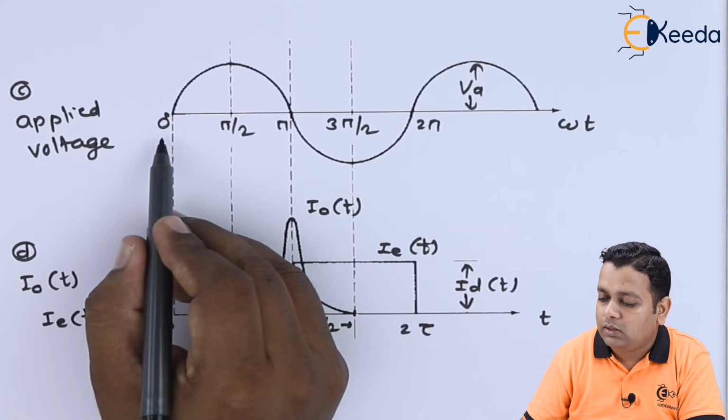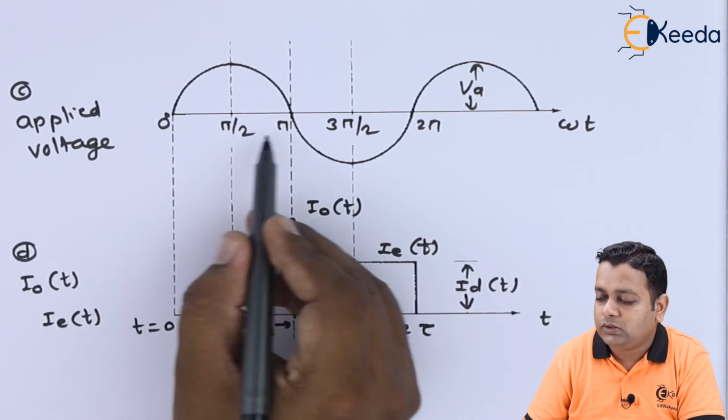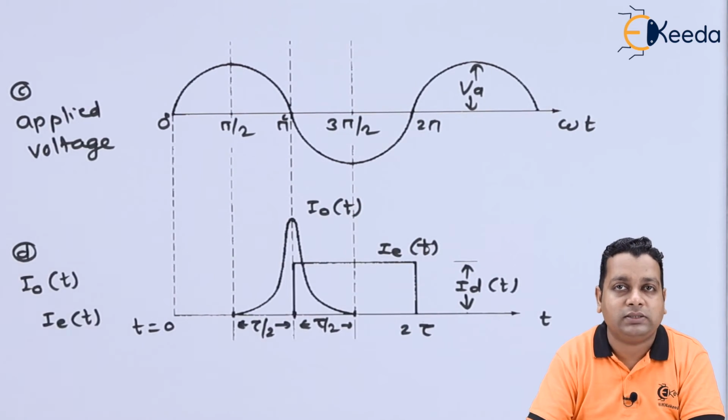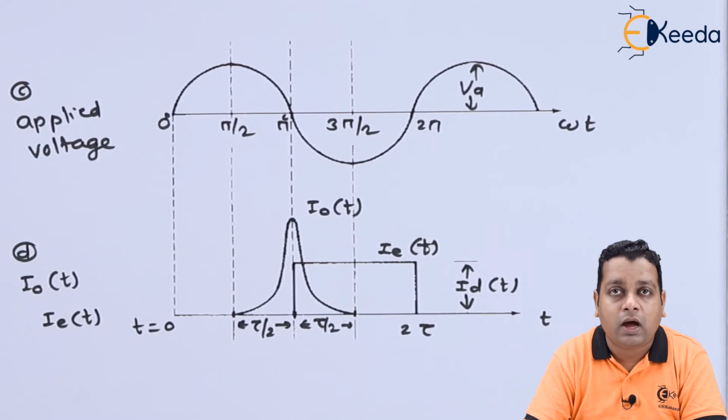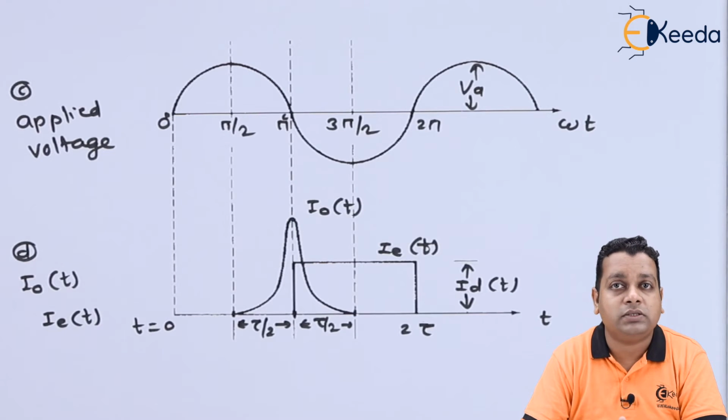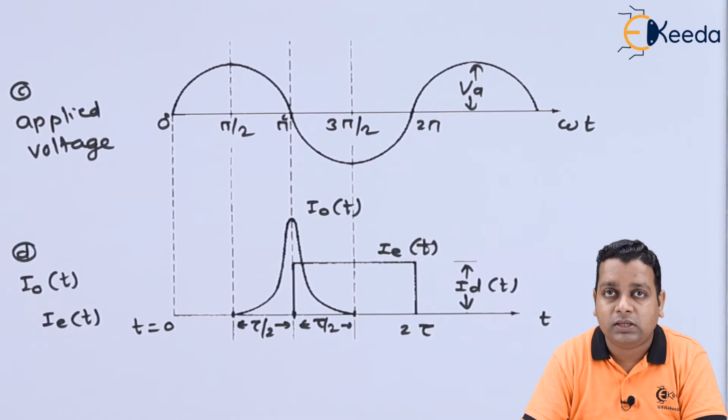If you can see here, after 0 radians, we have come to pi radians. Here radians can be represented like this. So this is 180 degree out of phase, the output with respect to the applied input. 180 degree out of phase means a reversal. This we can consider to be the negative resistance device operation. And when the device operation is exhibiting the negative resistance, it is nothing but generating the microwave energy in our case here.